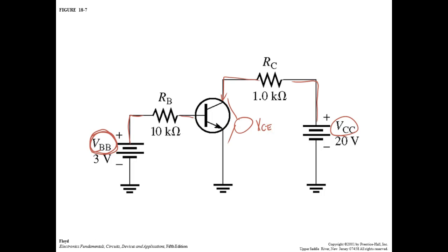So here we're talking about the voltage across the leads, and we give you the letters, right? All you got to know is the one on the right is your common. This is where you measure it relative to. And if I measure the voltage right here, what would we call that? We call that VBE. Where's your common going to be at? It's going to be on the emitter. This voltage right here, we would call this VCB. So this would tell you how you would measure those voltages. Of course, guess what? We can calculate all these. And once I've calculated them, then my measurements mean something. And this is what we're trying to do. And once we get a feeling of what these things normally are, then we don't have to do the calculations anymore.